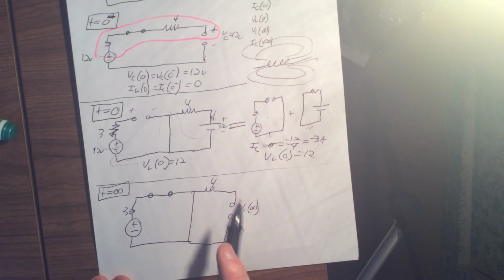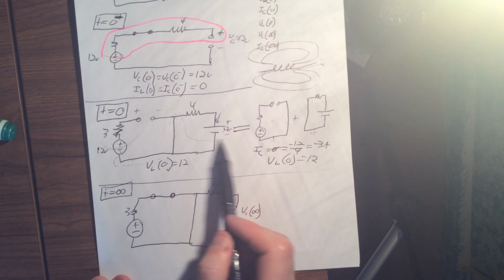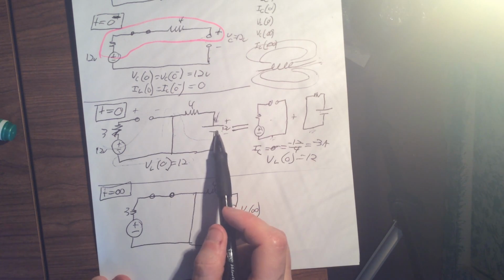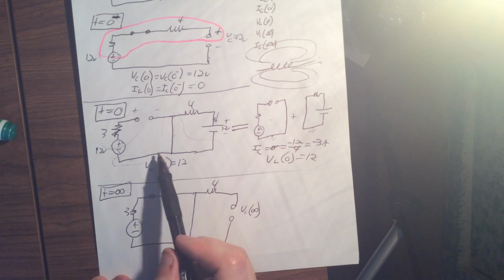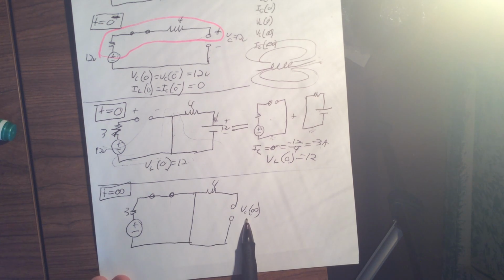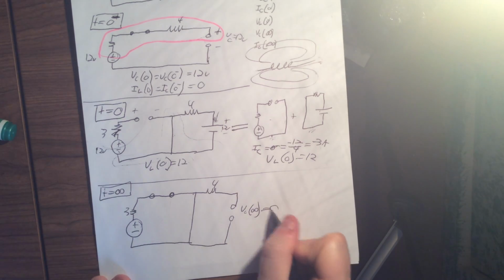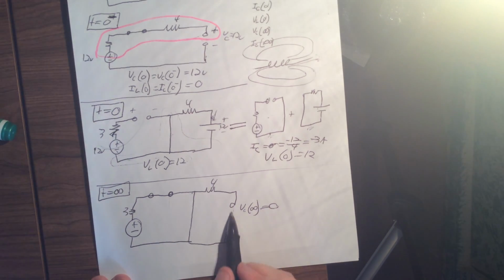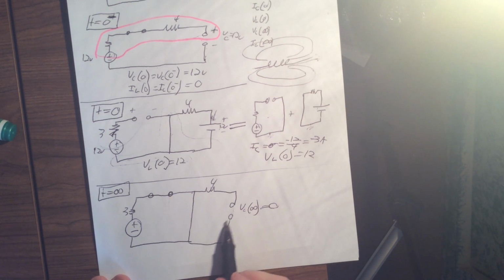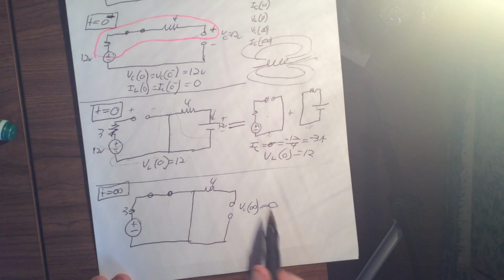So look, this is what we've done for this last part. Again, if we go up to our original circuit, the only difference between this and this is now the capacitor is fully discharged the whole way through, because remember, all this current is going to go around here. So this capacitor is going to discharge out and become an open circuit. So this VC equals 0. You could also have a line across here. Honestly, it really doesn't matter at this point if it's a line or if it's a hole, because it's going to be 0. There's no value there whatsoever. This is a little neater.